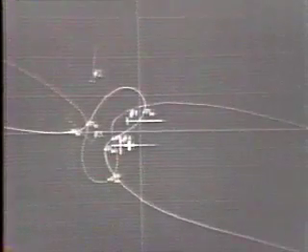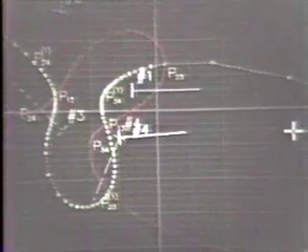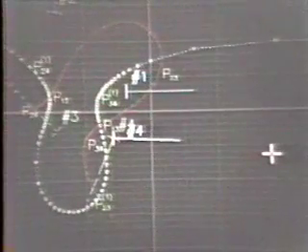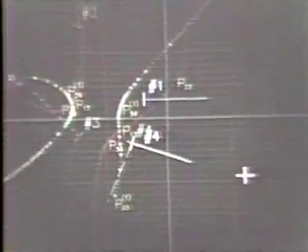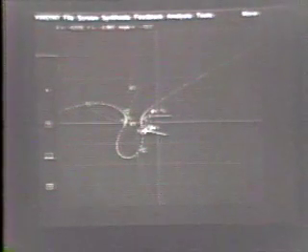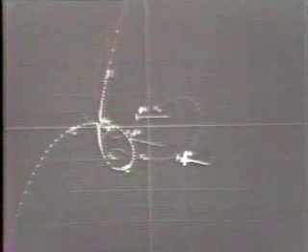Now the designer is putting out a fourth design position, and notice that the Burmester curves squirm around on the screen in response to the changing design positions. Powerful high-speed algorithms within Kinsyn 7 compute the Burmester curves and the coupler curves in real time so that the entire complete coupler curve and the complete set of Burmester curves can dynamically change before your eyes as you position the parts of a mechanism, either the design positions or the pivots on the screen. This makes it very easy for a designer to explore all the possibilities for mechanisms.